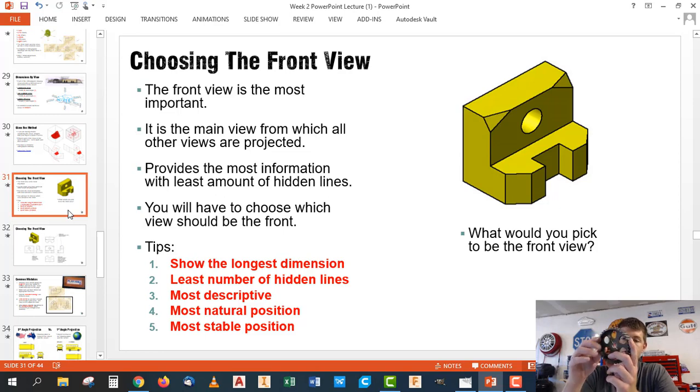So to make this final determination, if I was going to draw this, probably what I would do is I want the face that would be sticking out when it's mounted on the engine. I want that to be my front view, which would be this way. And then as far as rotating it, I'm going to put it maybe in its most natural orientation, or what a mechanic would call top dead center on the engine. That basically means where is this thing going to be rotated at when the engine is at the beginning of its firing cycle. So in this case, that's noted.